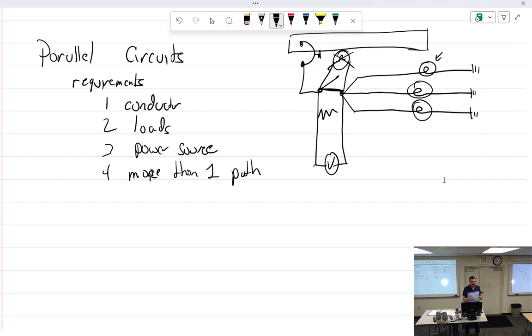Your little wires that you guys have that you're going to be doing a lot of stuff with, they have a fair amount of resistance. You can't measure it with an ohm meter, but start putting some power on them and you're going to see a voltage drop. So when I say to you, hey, how much resistance does that wire have in the circuit? What are you going to use? Use a voltmeter. We'll talk about that tomorrow.